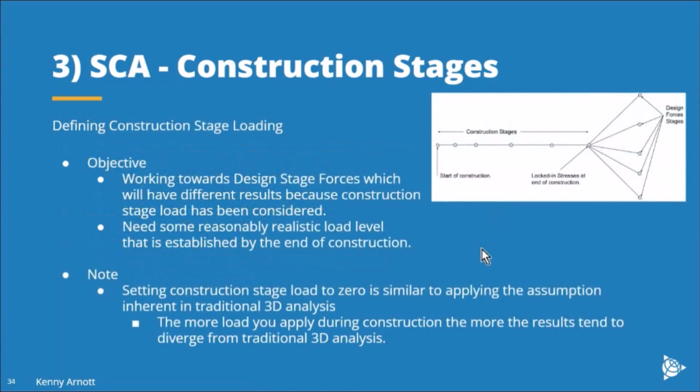So again, our objective, ultimately at the end of this stage construction analysis, is to get analysis results for all the same load combinations as you would normally have designed for. What we need to achieve at the end of the construction stages is this fully built model with some realistic load level established within that model.